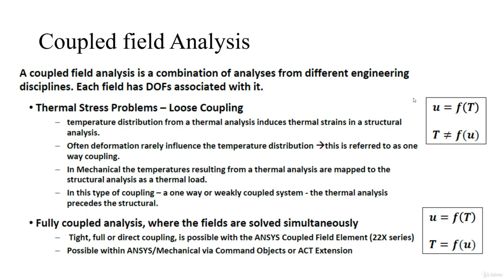And then in Mechanical, the temperatures resulting from the thermal analysis are mapped onto the structural analysis as a thermal load. In this type of coupling, one-way or weakly coupled system, the thermal analysis is going to be done first, and then it is followed by the structural analysis. As I've told you, whatever results we come across from this thermal analysis, we are going to take it as an input for this structural analysis.